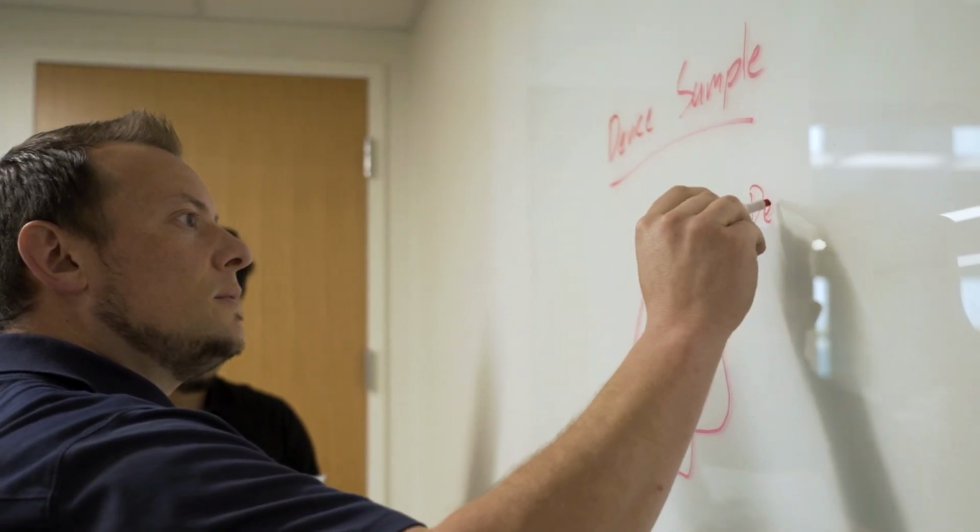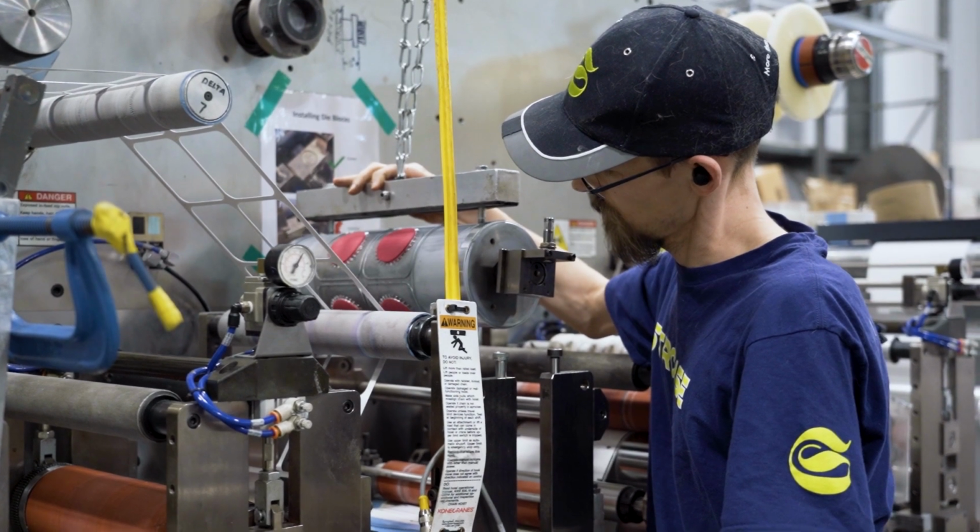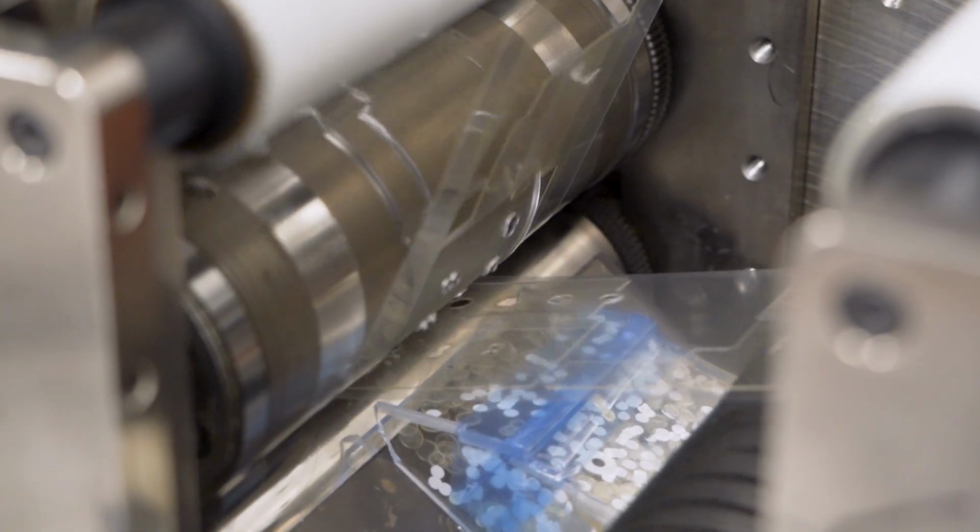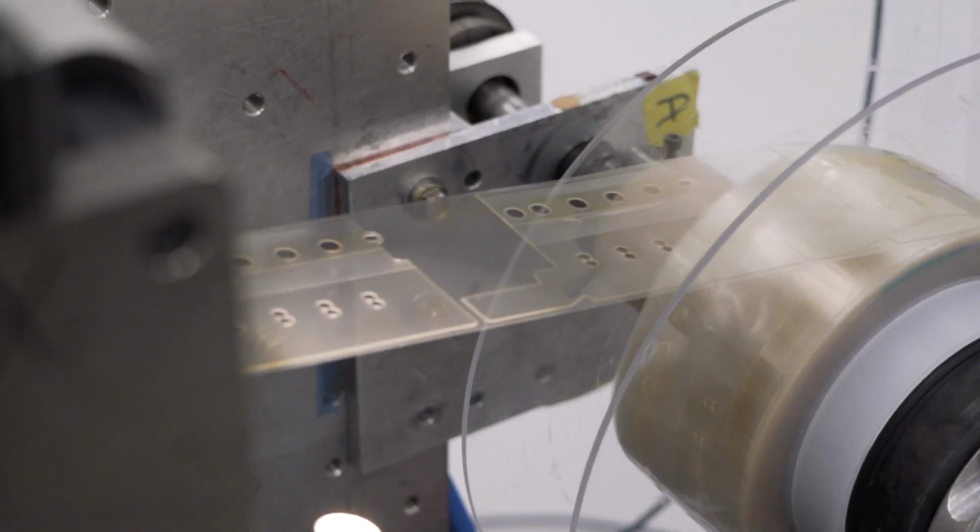It's necessary to specify measurements and tolerances because ultimately that's what we make our parts to. We're designing parts to make them in manufacturing processes, and it affects our ability to actually manufacture them. It also has a factor in cost. Tighter tolerances will tend to cost more than looser tolerances.